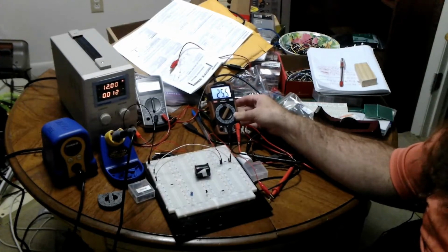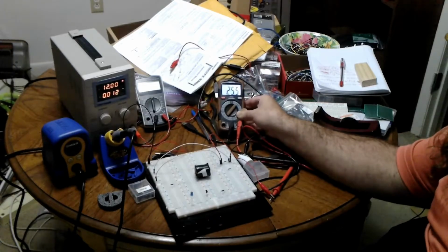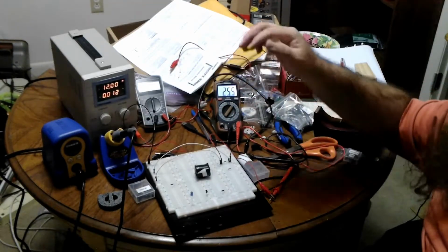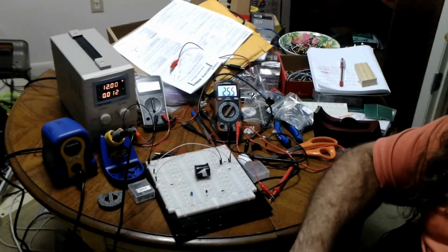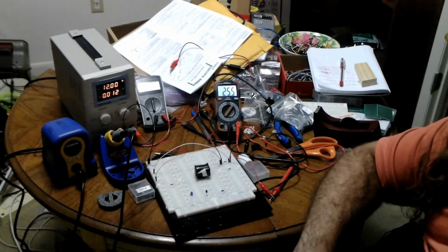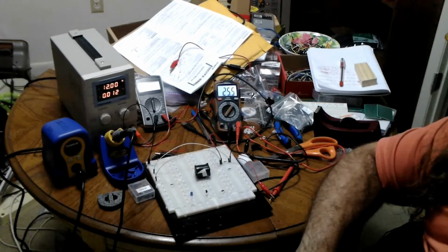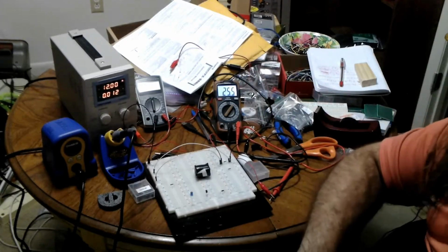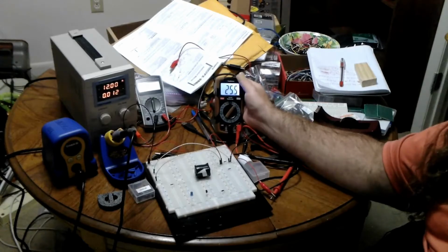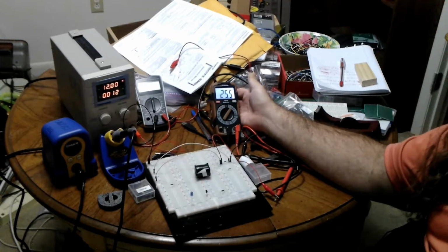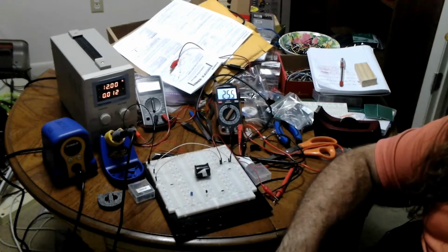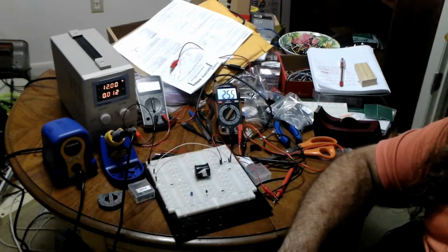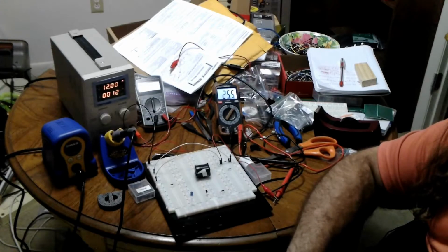The only thing on this entire meter that's AC is these two little AC voltages that are perfectly sized to measure wall power here and across the pond. 120, 220, a little bit more. That's the only thing that's AC on the whole meter. And while this was not a cheap meter, it was also not top of the line. So our first clue is, is there a way to use a DC meter to measure AC and just report it as if it was AC?